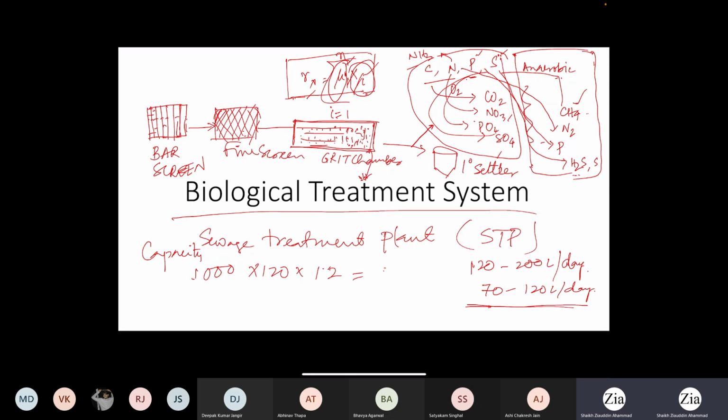So primary settler is essentially a settling device where the liquid will be introduced through a centrally located downcomer, and then the liquid will go up against gravity, because whenever you try to fill this particular system, liquid level will rise, so liquid will go up, and at the outside it has a collection.